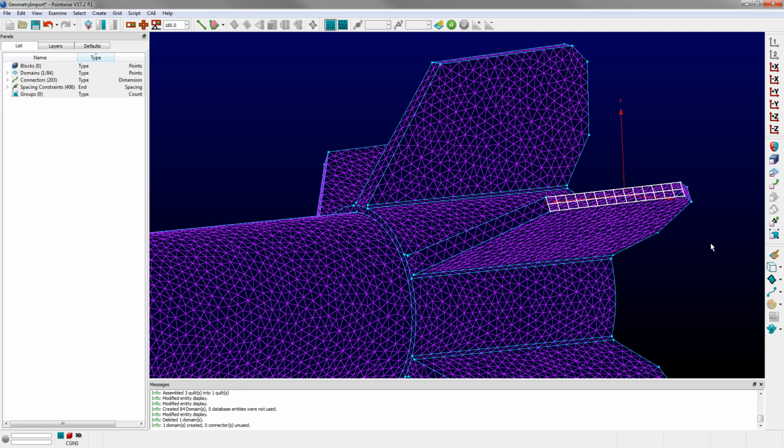The technique that I'm going to use to create my volume is TRex. I've talked about it before. It stands for anisotropic tetrahedral extrusion. It works by extruding anisotropic right-angled tets off of the surface in a way that they can be combined afterwards on export into prisms and unstructured hexahedra. It'll work off of tris and quads. You can have a mixed surface mesh of tris and quads, and it's going to work great. They'll be face matched and point matched at the interface between the two if you had a quad domain and a tri domain.